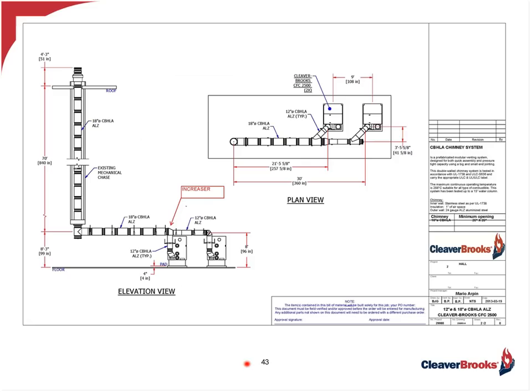If we consider an increaser in the breeching, as shown here in this elevation view, at the point of entry of the second boiler exhaust, we have now increased the cross-sectional area of the breeching to handle that increase in gas volume. Now let's take a look at that revised draft calculation.